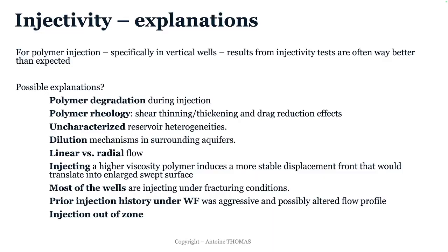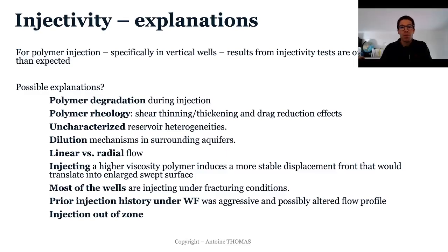So if I have to summarize these possible explanations, there will be factors linked to polymers, factors linked to reservoir, water quality, and of course the geomechanics, and obviously the history. So before polymer injection, what has happened? How was my voidage? Did I create some preferential path, and in which directions, etc.? So you will see that the most important things in this area are basically the presence of fractures that we will discuss a little bit after.